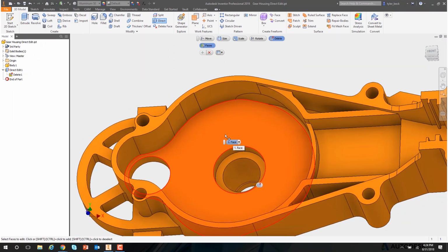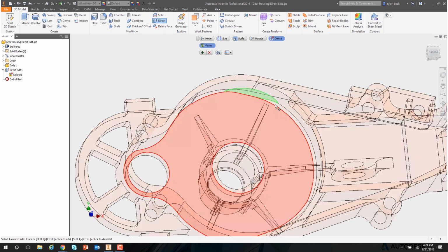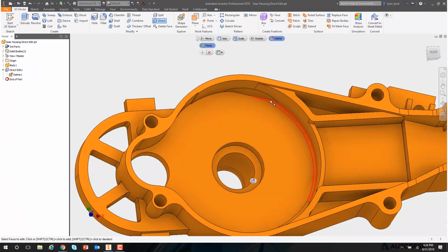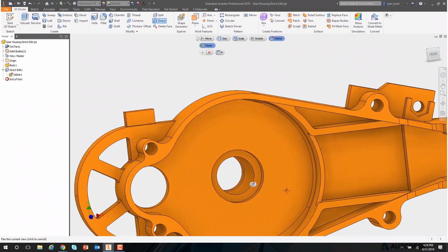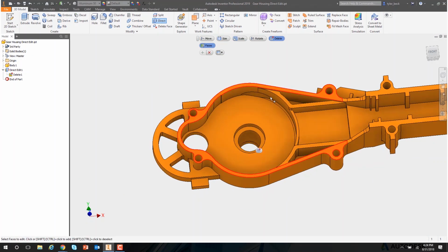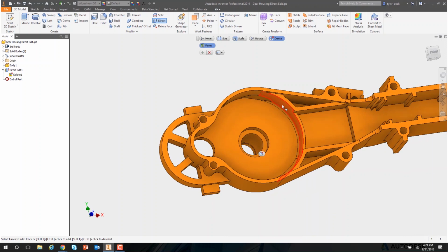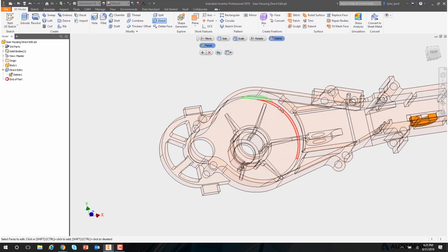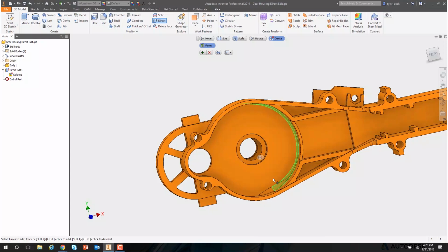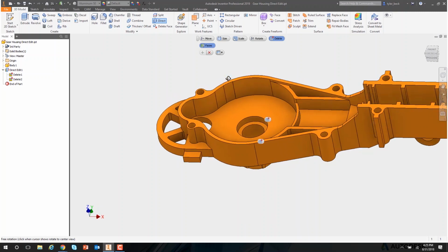Another challenge that we're facing cleaning up this model is they sent along this nasty fillet. It's got a kind of a variable radius fillet. I'll hit escape. Got this kind of strange fillet, and then even two parts to it over here. I'm going to try to select all of that and remove it. Once I select everything, then when I hit the delete, hit apply, hopefully I'll be able to remove that fillet and fill it back in. It does a nice job of that.